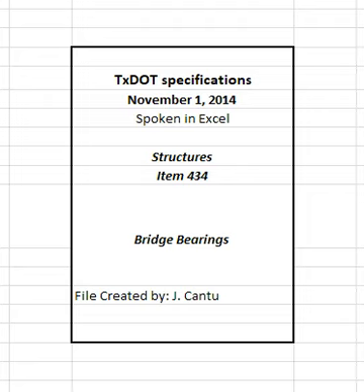2.3.1 Structural design. Provide a fabricator-developed design for the HLMR, disc or pot, bearings, meeting the service and factored vertical load capacity, service and factored horizontal load capacity, rotational capacity, and translation capacity requirements indicated on the plans and augmented by the requirements of this item. Provide a bearing capable of transmitting 15% of the service vertical force as a factored horizontal load if no horizontal load capacity is provided on the plans.